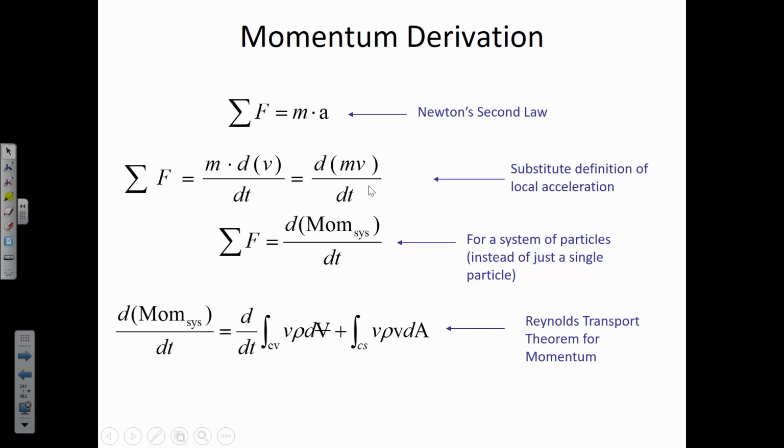Okay, so remember Reynolds transport theorem. It says that we're going to be looking at accumulation of something inside of the control volume and flow of things through the control surface. In this case, we could look at the flow of momentum through control surfaces, because on the inside of this integral, what we've got is the velocity of the fluid, density, velocity, and area.